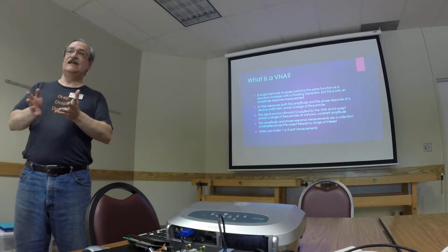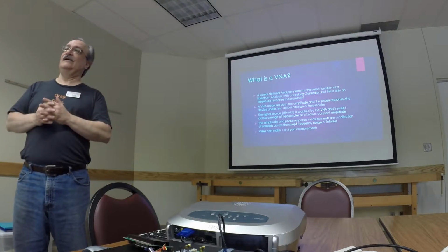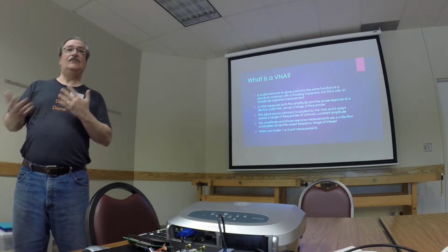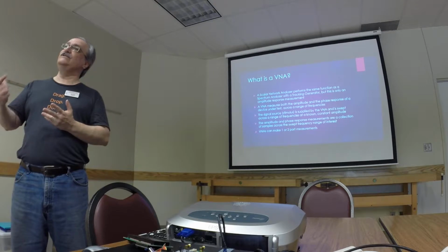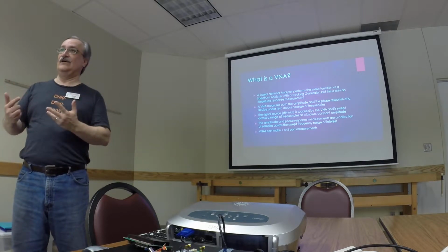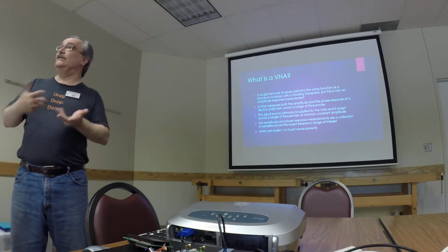Then you can use that to test filters or other devices. You can actually tune your antenna with it. There's a number of things you can do as long as you have a directional coupler or a bidirectional coupler. Directional coupler is the most common kind, and that gives you reflected only.